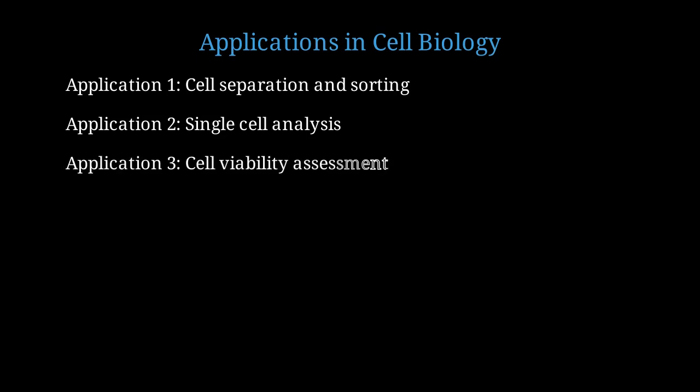Third is rapid cell viability assessment. Dead cells have different electrical properties than live cells due to membrane damage. Fourth is droplet manipulation in digital microfluidics. We can move, merge, and split droplets containing different reagents.